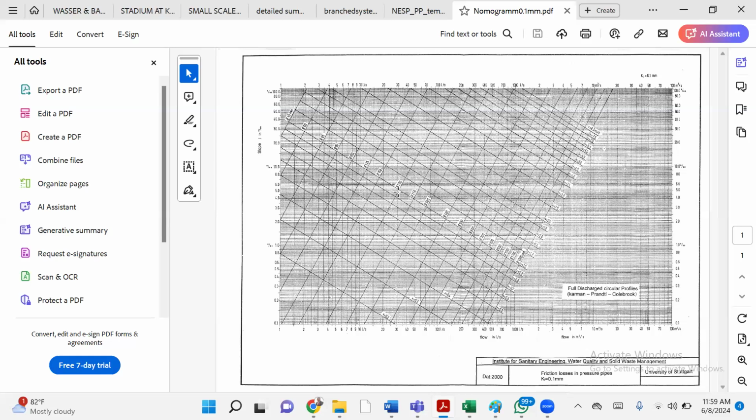Yes, sir, it is. So you can see that if I'm asked to design a water reticulation for a district, a village, a state, whatever, of 15,000 population equivalents, which if you break it down is 50 streets with 30 houses each, you have to choose how you derive your population equivalent. All I want is your population equivalent. If you multiply it by the requirement of one person and by the peak factor, it gives you the water demand of that place.